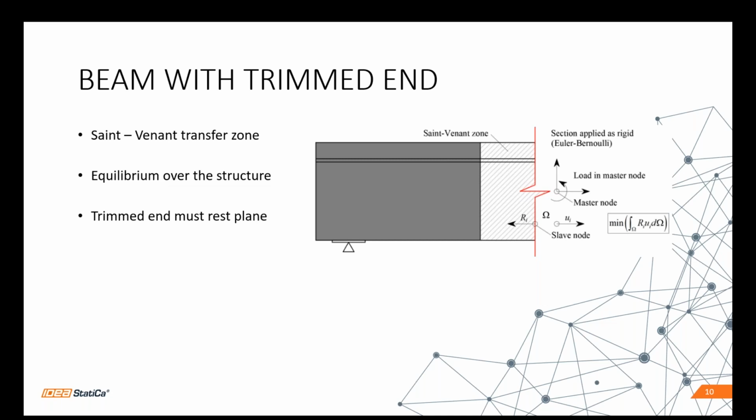If you check it with your global model in some third-party FEA software, you ought to get the same or really similar values of internal forces as in the IDEA StatiCa Detail application. To ensure realistic stress distribution in the analyzed part of the structure, the Saint-Venant zone, the transfer zone, is automatically created by the software, so you don't need to model it yourself.